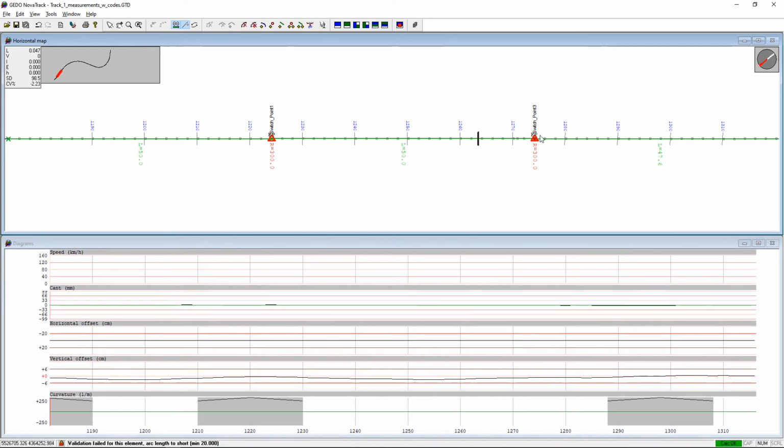It might be that at some point the previous control points from the previous radial element have drifted, so there is no need to worry about this. If this happens, you just need to put these 2 points one over each other. So it's like this, and then we again have this straight line in between, snapped exactly at point 1 and point 3.